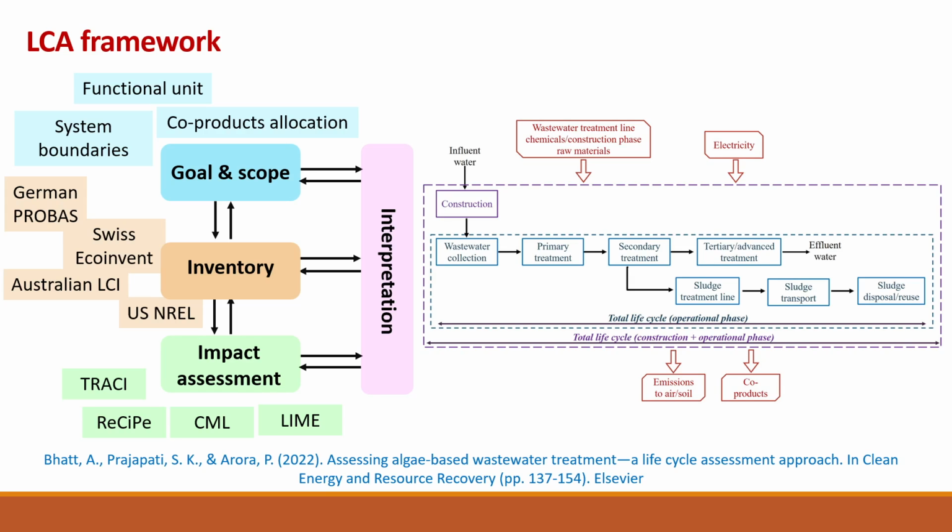What are system boundaries? You create a boundary around the unit processes that you want to consider. If I'm not interested in the construction phase and want to go only to the operation phase, I'll just exclude that, so it will not be included in my system boundary. Depending upon your goal, you have to consider the different operations or processes for your LCA. Then in the second step, you will conduct an inventory analysis for each of these processes.